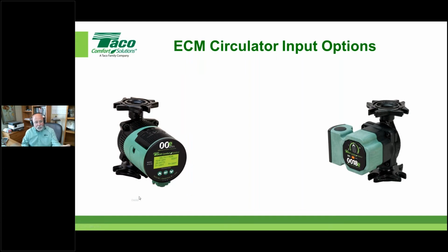So we've got the good old Taco Delta T pumps that have been around for a long time. You understand that the input to one of those is 2 sensors in the Delta T mode, or if it's in a fixed speed, fixed temperature mode, it might just be 1 sensor that it's looking at. But understand the input in those conditions are 10K thermistor readings that give the circulator the input it needs to make a decision.